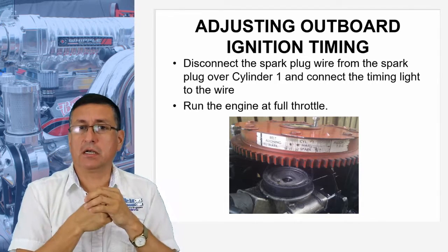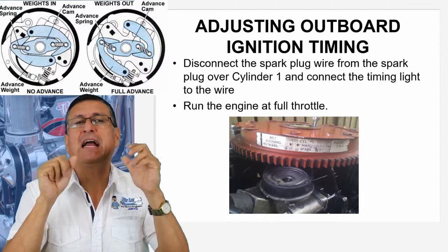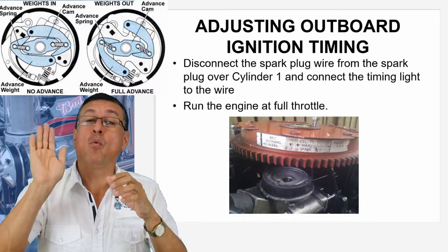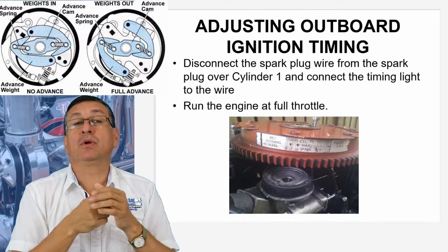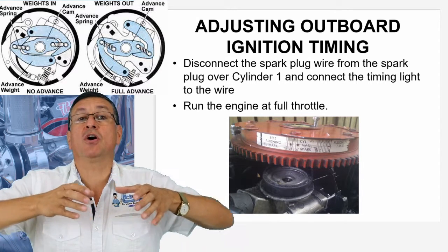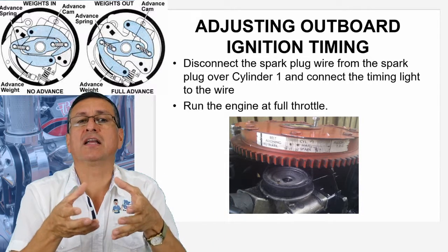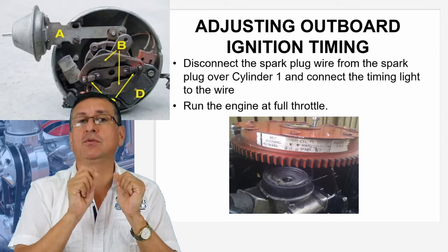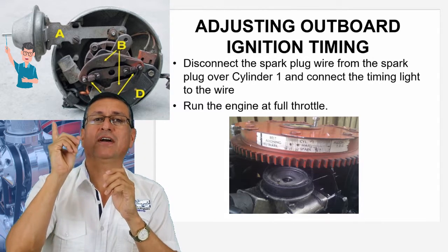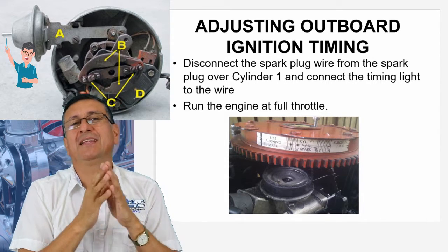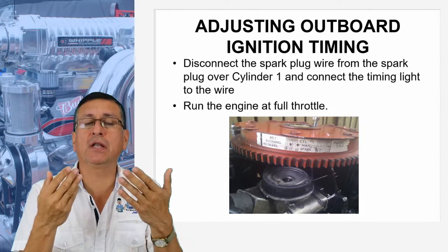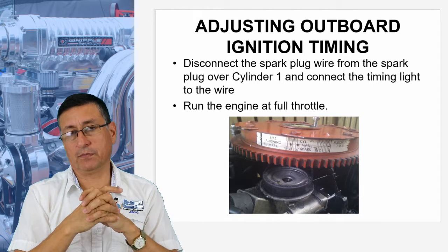How the inboard engine with the electromechanical system calibrates the timing for wide open throttle and heavy loads is with counterweights located in the distributor. Those counterweights, according with the RPMs, open and close and advance or retard the timing, according with a vacuum valve on the side of the distributor. That vacuum valve is for timing adjustment. This is in all versions. I never mentioned that because every day they are less popular and I would create confusion.